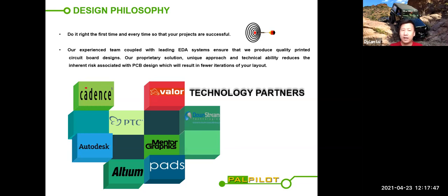So if you make any move on the layout that violates any of the rules that you have already set up in the Constraint Manager, the software is going to show a big bow tie shape with a 3-letter word, DRC, on it. DRC stands for Design Rule Check. So it checks you and says, boom, something's wrong. You violated a rule: either fix it, or if you did it intentionally, you need to waive it. Okay, so it provides a very good aid to the designer to do a good job.